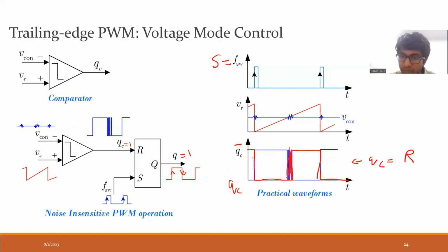If it becomes 1, then goes to 0, again becomes 1, again goes to 0, this will be off only. It will not change. We do not want it to turn on again. Once the signal comes and you switch it off, it is switched off. Even though there is a certain transition, it will not turn on. That is why we use this SR flip-flop, SR latch, for implementation.